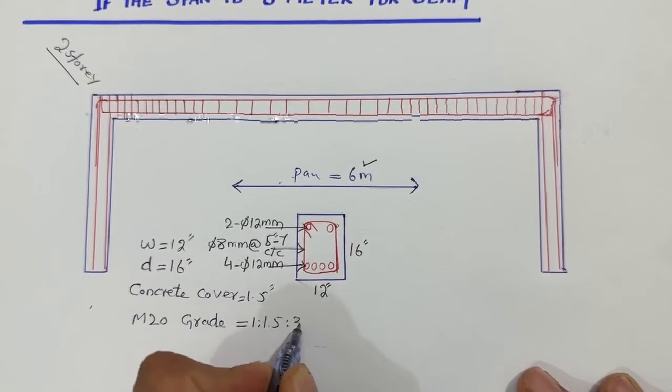Next guys, you can see the development length is very important. The top bar is going to the downward side and the bottom bar is going to the upward side. So the development length is also very important. It should not be less than 12 inches. So let me write here LD, development length, right? So guys, these are the details, especially for the beam.